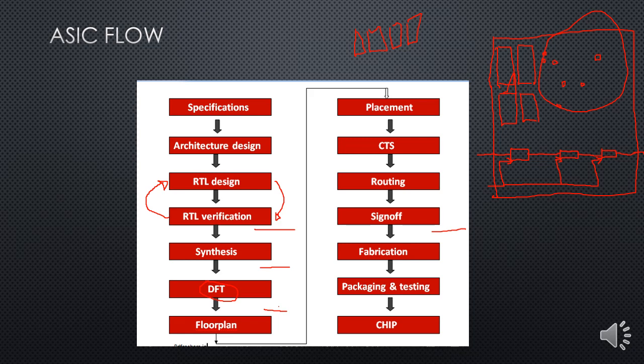So that means, as I said, in order to provide this input and see the output, we now require 3 cycles. That means from the first cycle, the data reaches here, in the next cycle, the data reaches here, and in the third cycle the data reaches here, and then it goes to my output. So we need 3 cycles in order to take the data from the input, process it, and give it to the output.